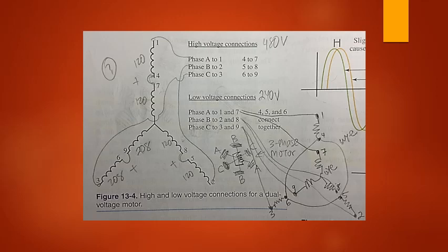The wound rotor motor. The wound rotor motor uses a stator constructed like a regular three-phase induction motor. However, its rotor is made of three sets of windings wrapped around soft iron laminations. The three sets of windings in the rotor are connected to slip rings and brushes. The rotor circuit is connected to a rheostat. The windings are similar to the squirrel cage rotor.